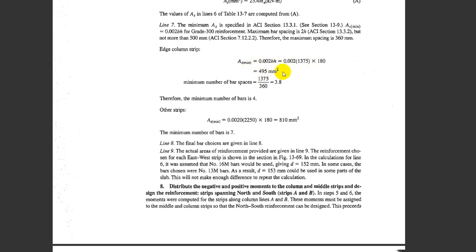Because the rebar area for 16 millimeter diameter will be around 200. So this is a little less than 3 16 millimeter diameter, but you need 4 for minimum,